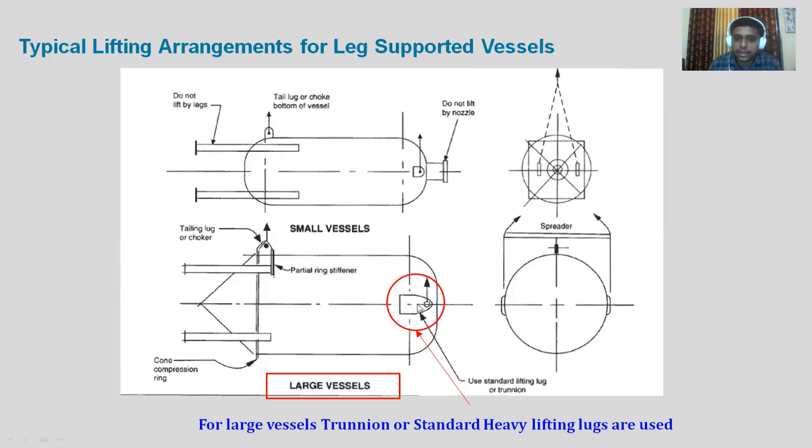One is the strong axis and another is a weak axis. Strong axis is across its width, like here. So there will be some forces acting like this. Because of that, there will be some bending moment. So the stress caused by the bending moment will be calculated as stress equals M upon Z, that is, M is the bending moment divided by Z, the section modulus. And in this case also there will be some force acting. Because of that, again the moment will become. But here the section modulus will be the strong axis section modulus, and here across thickness the section modulus will be the weaker section modulus.